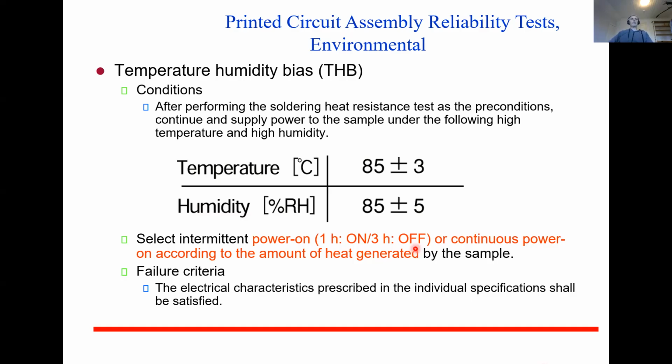Okay, but anyway, the point is that you have a certain parameter, typically a resistance, which you monitor during the exposure, and based on that, you try to estimate the effect of this kind of hot and humid condition on the reliability.